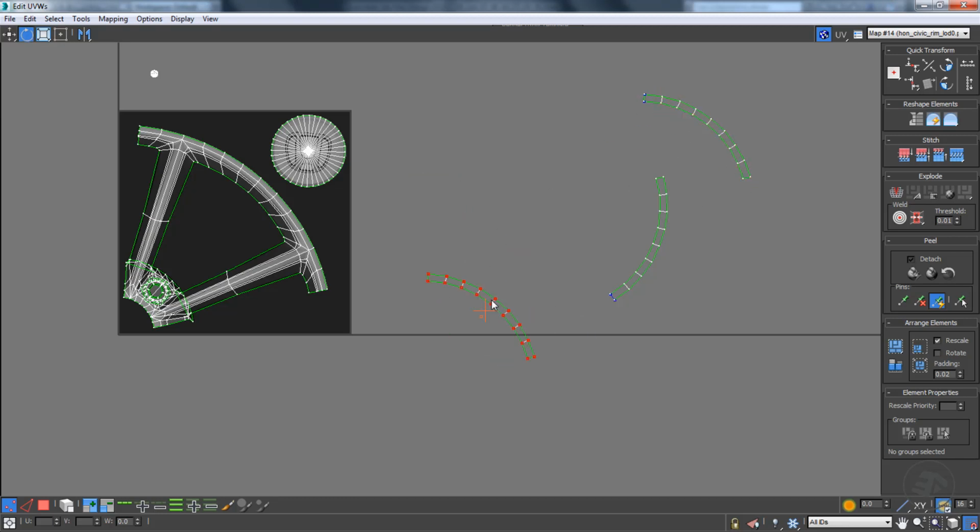You can optimize UVs by breaking symmetrical parts and overlapping them. Pack the unpacked UVs on empty space over the map or the texture.